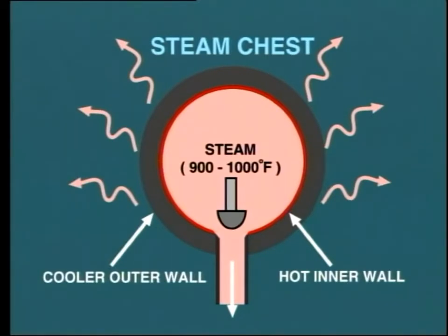So, what problem could this cause? Well, the result is that the inner surface tries to expand at a greater rate than the outer surface. This could, after many cycles, lead to cracking on the outer surface. But it does not always work that way.